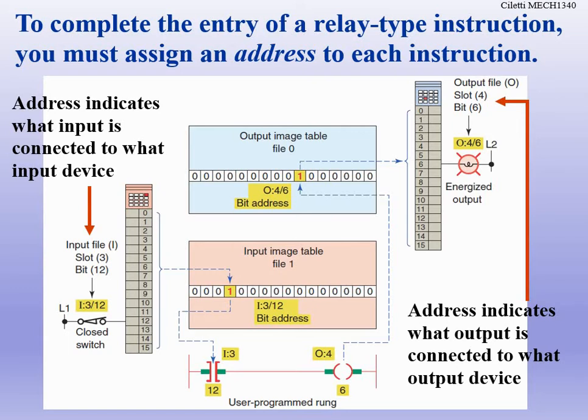Every program we write, we need to go in and make sure that we change the I/O every time we set it up. And I've emphasized that in my videos where we set up our PLC and make sure that we are changing the correct input, because it defaults to like 126 and things like that with our 1500s when we first start out using the TIA Portal. So it's using slots that we don't even have. So we need to make sure that we are changing our inputs and outputs to start correctly in our program.